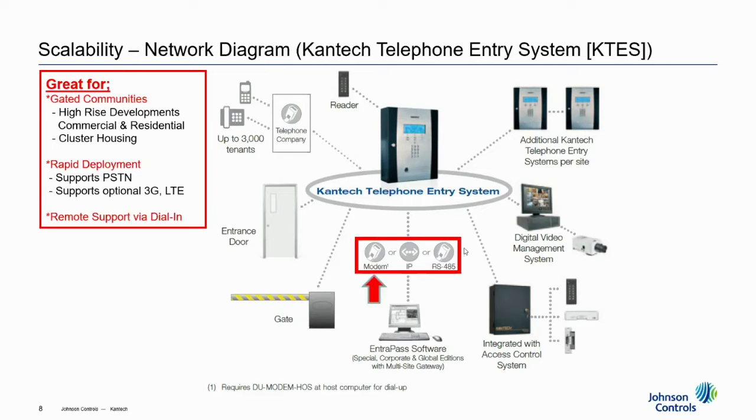And in terms of managing this product, it can perform as a standalone, meaning that you do not need to connect to the EntraPass server 24/7. So in terms of programming this KANTECH telephone entry system, the KTES, you can do the configuration in 3 methods. You can either configure them using RS-485, IP, or even dial-up modem.